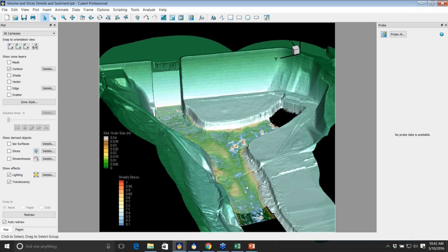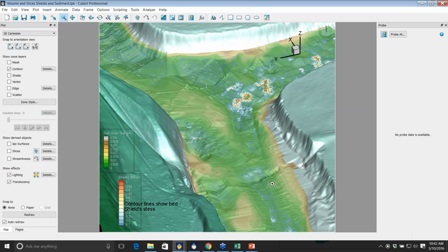And what I've done, once again, it was fabricated data, but I took a couple hundred points randomly picked throughout the reach and said if we had done bed material sampling, if we had a grain size, and I put that in at XY coordinates, and then let the Cubeit software carry those sediment distributions through the whole channel. I then followed the equations we looked at before, and I calculated the shear stress, and then here I'm showing this parameter, Shields stress.